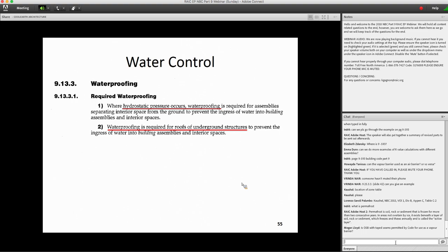When we have the water table higher up or at the level of our footings or footing walls, some areas we do have the water tables pretty high, or in areas where we want to prevent flooding or excessive rainwater in that particular plot or lot from getting into the house, we want to have waterproofing.